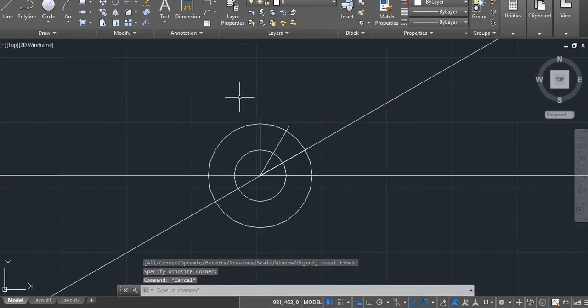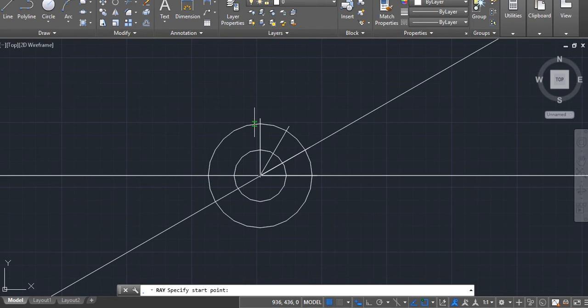And now let me introduce you to the ray. The ray tool is a construction line that doesn't extend throughout the screen, but extends through one area of the screen. Let's see how that's done. So for the ray, I'll be choosing 2 points, just like construction line, point 1, point 2. And automatically, AutoCAD will complete the line drawn that way.